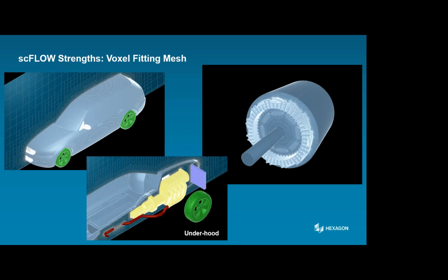However, sometimes this kind of discretization can become tricky when the system has a lot of different components with a lot of small details to replicate. In this case, a large amount of human time would be required just to proceed in CAD geometry defeaturing and simplification, and to prepare the geometry for an efficient meshing process.